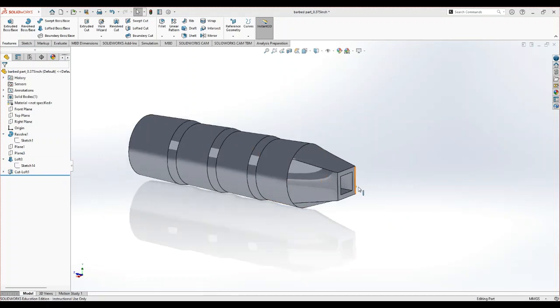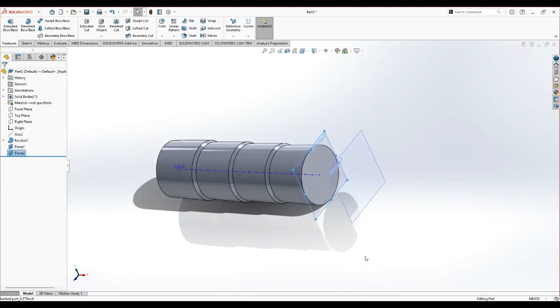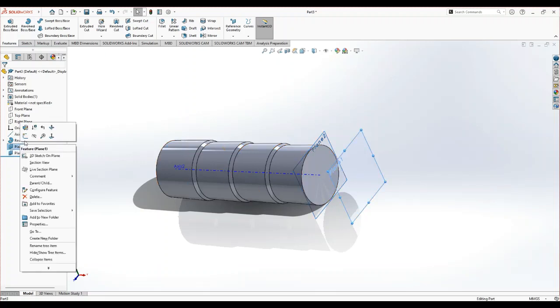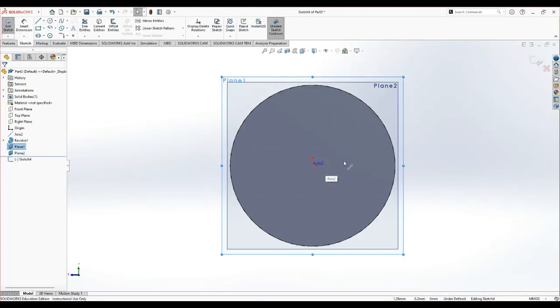And what you can see is we're connecting that circular edge to a square. You can think of a loft as an extrusion that's connecting two sketches or two geometries. And right now it'll be that circular edge and then a square, which means we need to go ahead and create that square. So we can do that. We can highlight plane 1, add a sketch, press the sketch plus button.